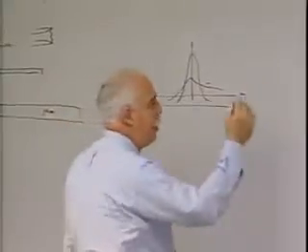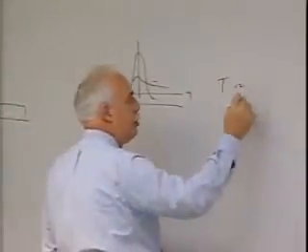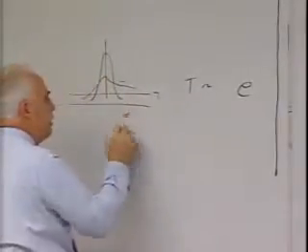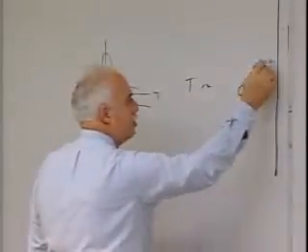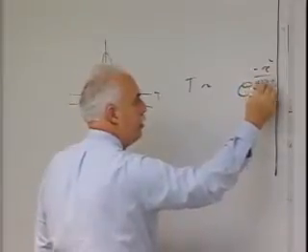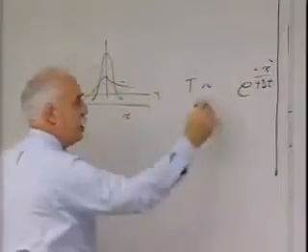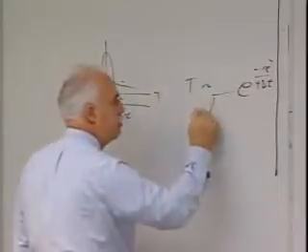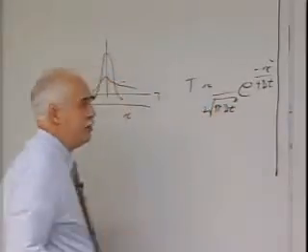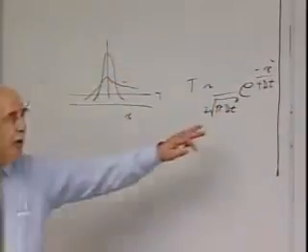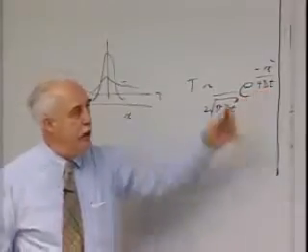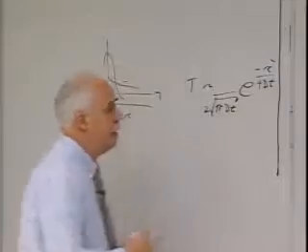Okay, the functional form of that, if you recall, T is proportional to an exponential of x squared over 4 thermal diffusivity times time, and there's a square root. Think of it as a one-dimensional normal distribution, except instead of 2 variance squared here, you've got 4 times the diffusivity time.